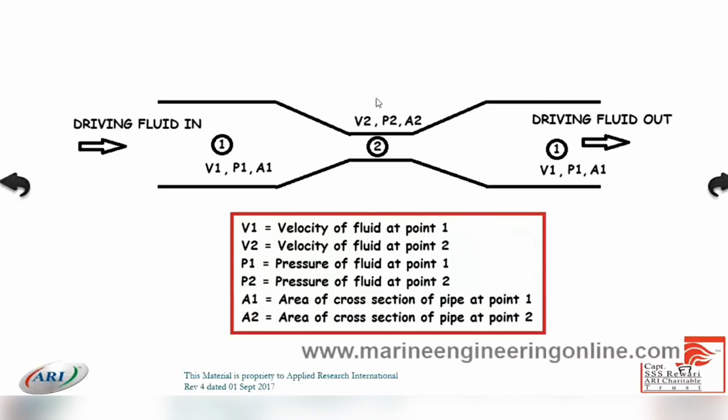Flow of current is there. So when the same amount has to pass, the speed will increase under the keel, between the keel and the bottom. As the flow and speed increase, low pressure is generated, and there is a high pressure from the ship, so the ship squats.